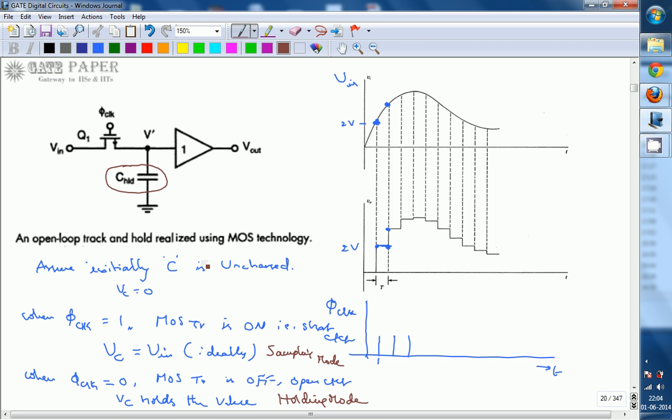Okay, so first of all, this is the ideal sample and hold circuit, but practically what happens is that the capacitor cannot charge instantaneously. The capacitor definitely requires some time, and it charges with respect to some time constant, which is the resistance of the switch. Within no time the capacitor is expected to charge to the input voltage, but it doesn't; it takes some time. That time is called the acquisition time.